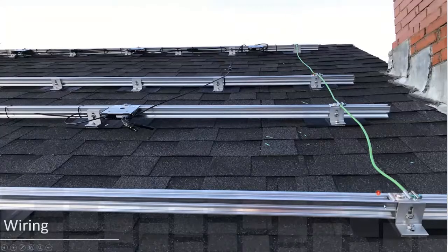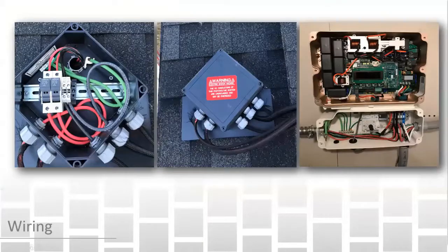So you can see my bond wire run here between rails. You can see, in this case, these are power optimizers. Microinverters would be similar. They're all interconnected. And the positive negative feed-ins are just waiting to receive the actual modules that will go on top. Then I'd finish up my wiring.